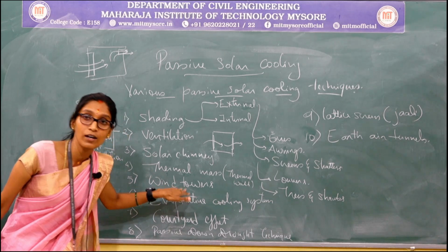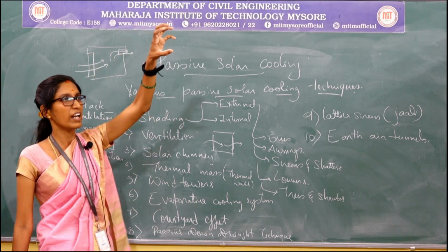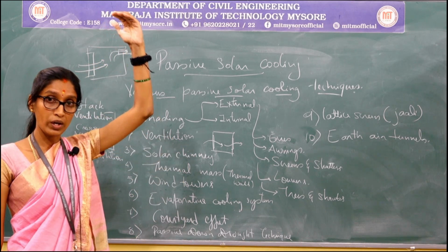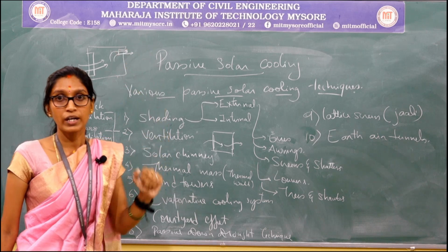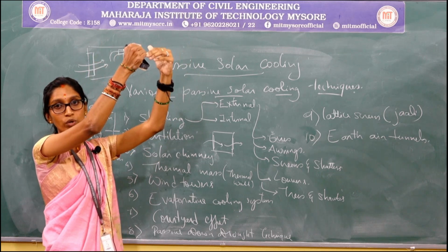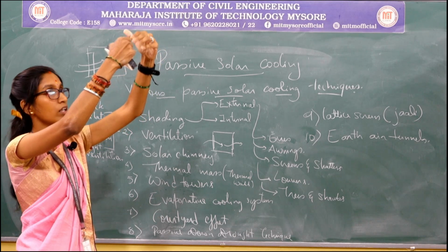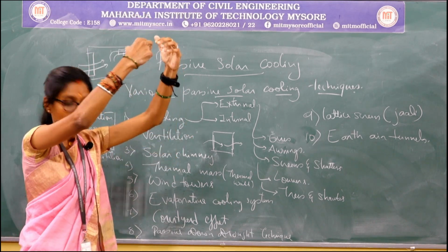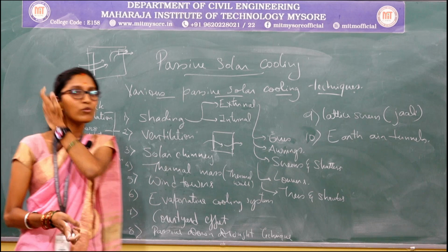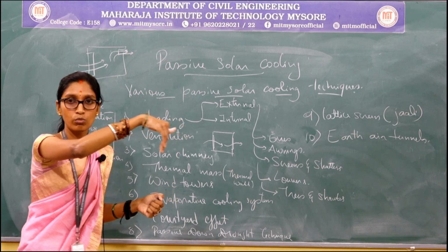And these systems, in order to have a greater absorption of air or a high movement of wind in a particular building, are placed at very high elevation, where good, fresh air will be trapped and move inside. Okay, once it is moving inside a wind tower, what is happening? It is being drawn down. It is going to move in a downward direction. What is going to move downward? The wind which is directed into a building is going to move down, right?